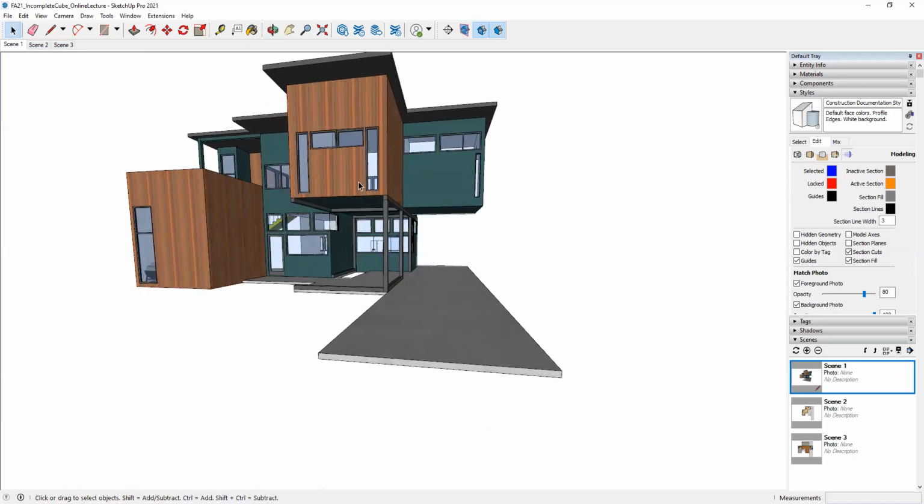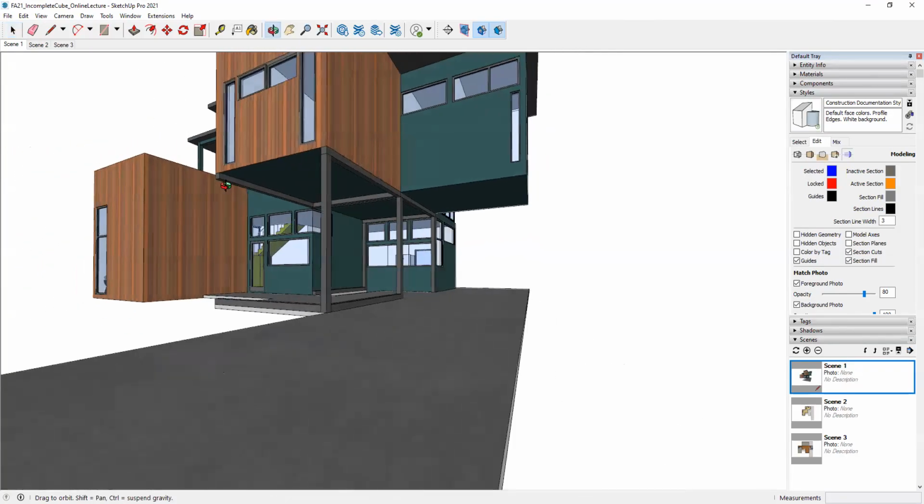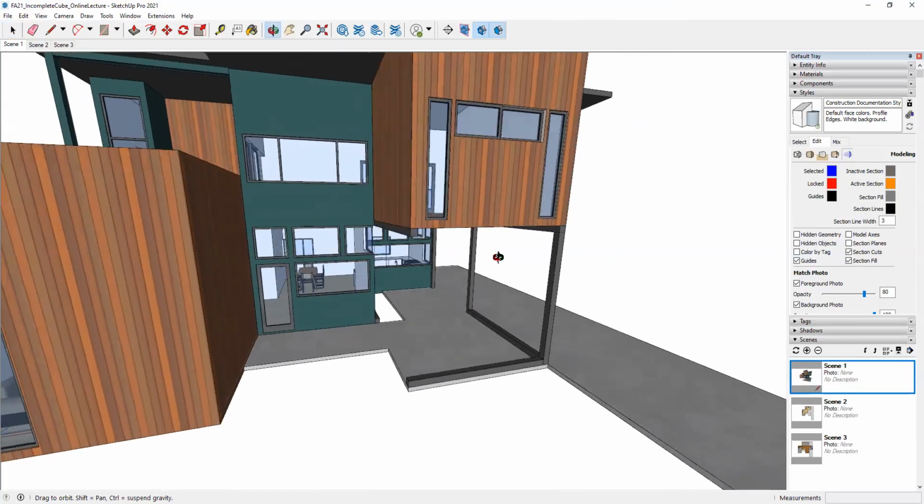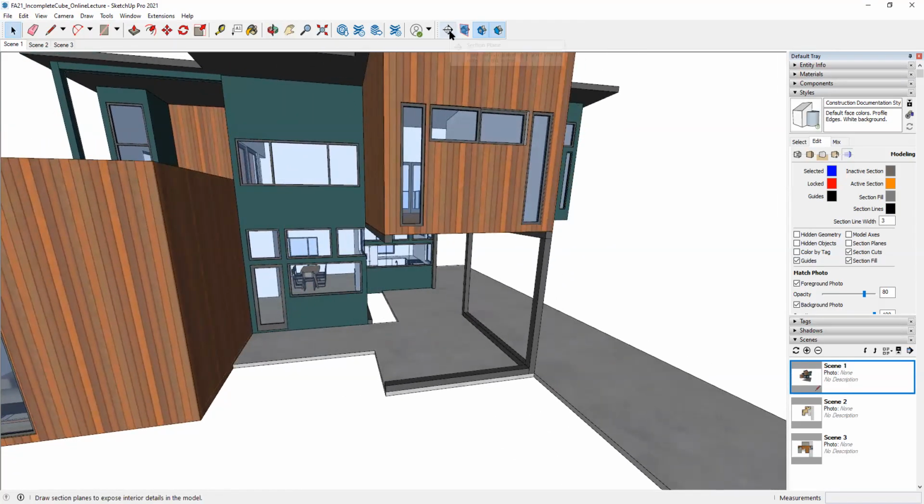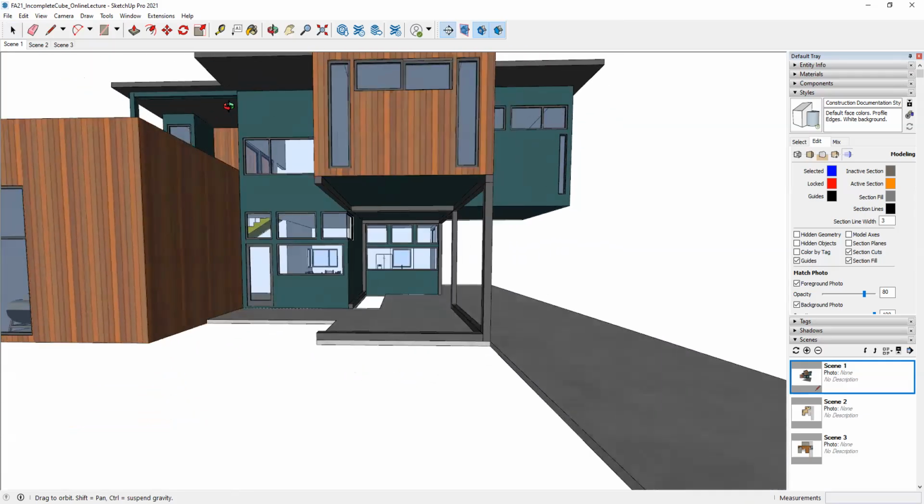Next up is going to be the reflective ceiling plan. Now I said that floor plans are cut 4 feet above the finished floor. Well, reflective ceiling plans are cut 7 feet 6 inches above the finished floor, and they're looking up. So what I'm going to do, and now this is going to be a tough one, because as I mentioned, here, let's go ahead and start. We'll create a section plane.